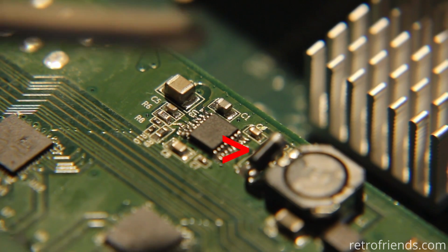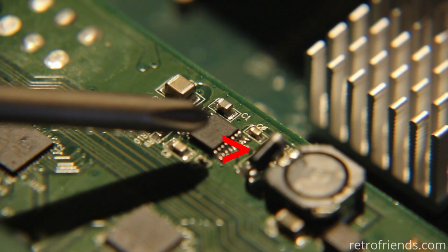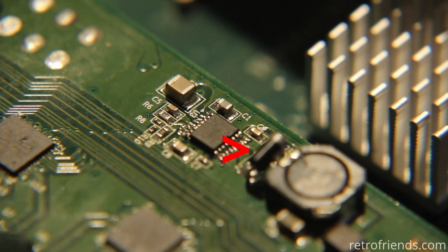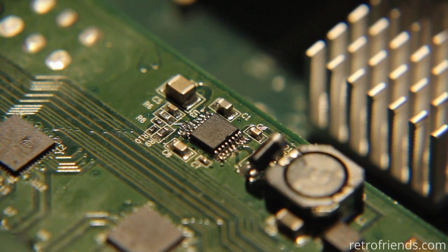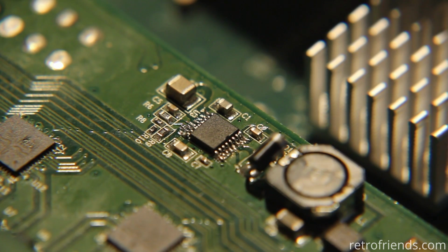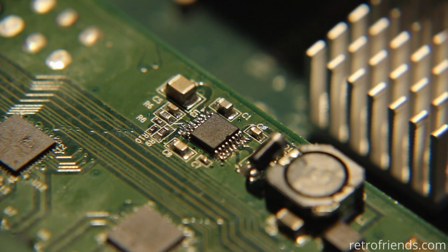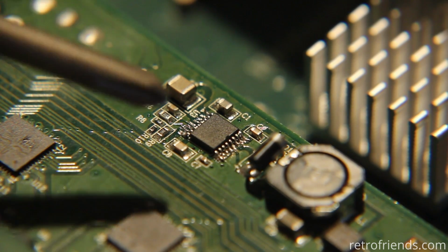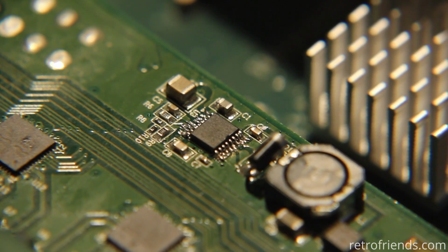And I thought, oh no, I got my 2 pins shorted, because it's 2 pins of this that go to the diode. As far as I could tell, I didn't make a mistake there, so I decided to take the diode off, and sure enough, the diode itself was shorted. It wasn't me. So anyway, I got that done, and we're going to test it out.